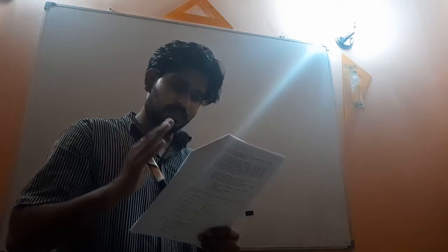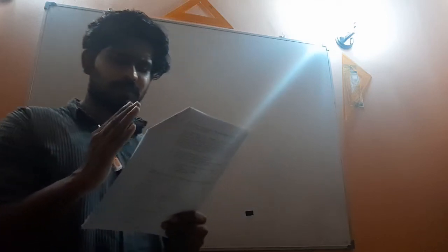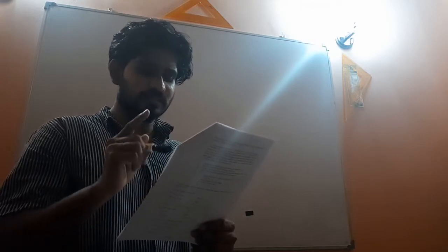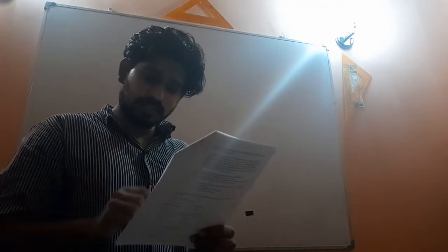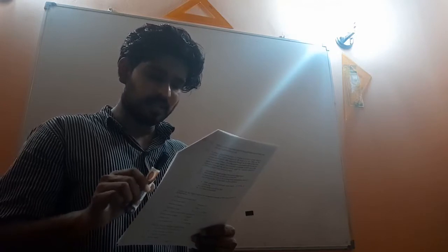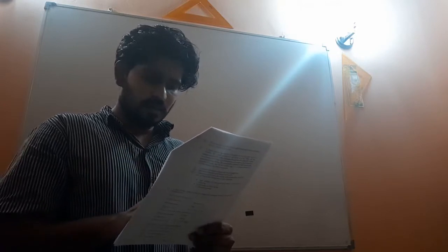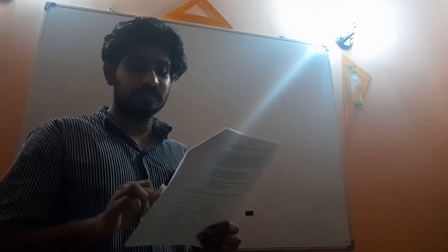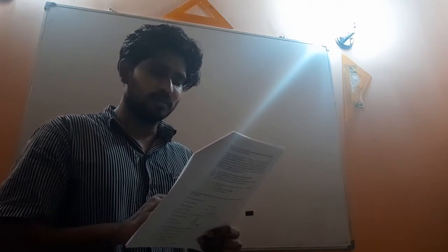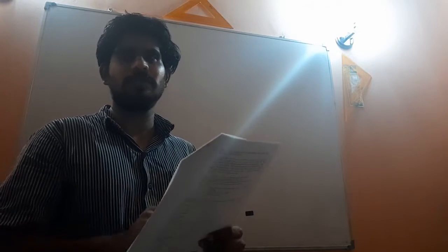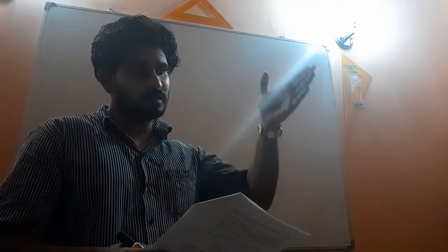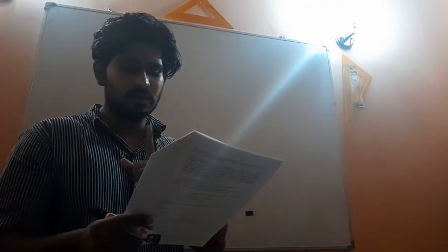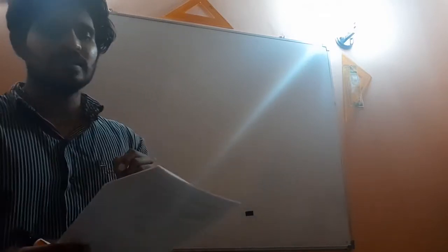In a steam power plant, the inlet state to the high pressure stage of the steam turbine is 40 bar and 350 degrees Celsius. After expansion, the exit steam of this stage is dry saturated, right? The steam is reheated at constant pressure to 350 degrees Celsius before being expanded in the low pressure stage to 0.7 bar. That means the final turbine stage, the second stage turbine process, ends at 0.7 bar, right?